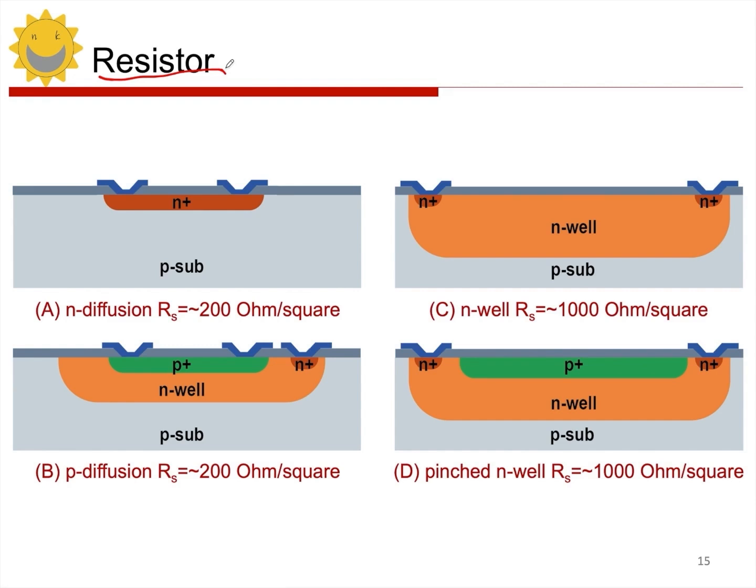Generally, they only provide one type. For example, for a specific feature size, like above 0.5 or below 0.25, they might only give you a MIM capacitor. So when it comes to capacitors, you generally don't have options. There's only one type available. But resistors are different. For the same process, resistors can offer you quite a few options. Now let's take a look at the different types of resistors and what distinguishes them.